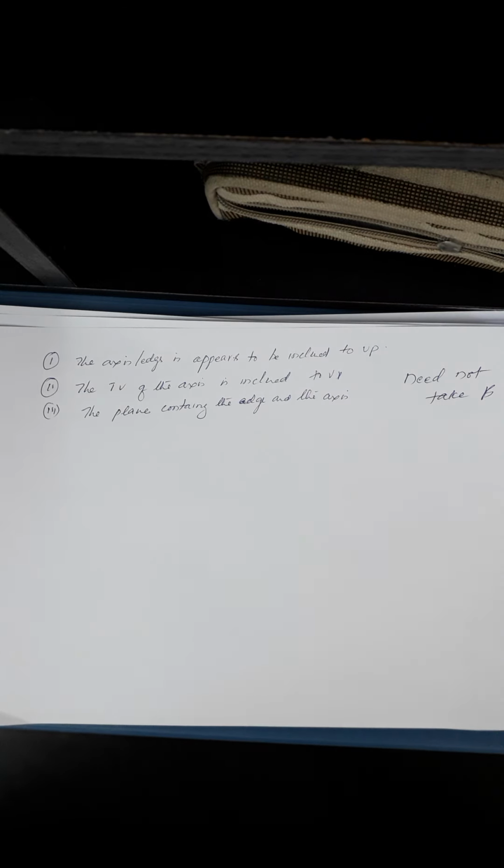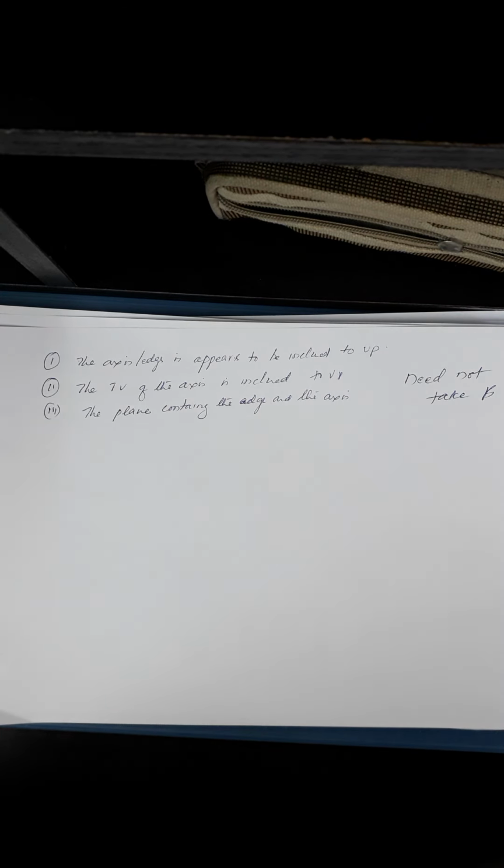So in that case, now you're going to find a problem something like this. A pentagonal prism of 30 mm base edges and height of 70 mm is resting on one of its base edges on HP such that the axis is inclined at 30 degrees to HP. In that case, it can give you the axis or the base, or the rectangular surface containing that edge on which it is resting is inclined. In that way, it can give you one inclination.